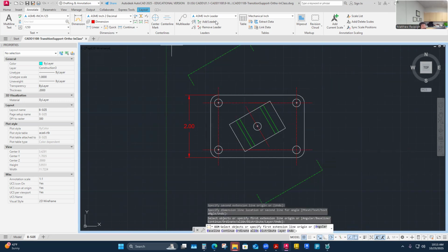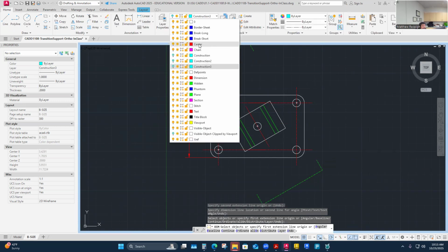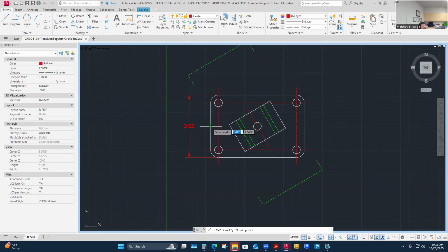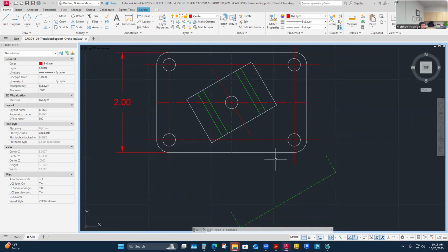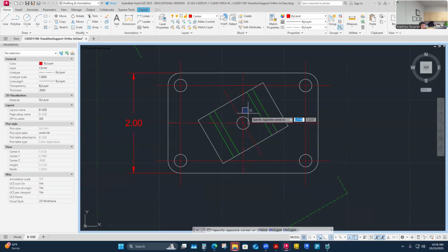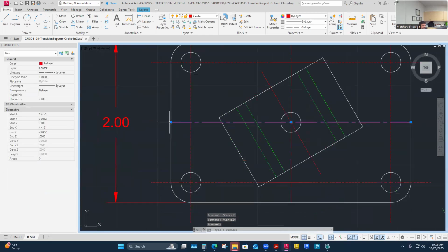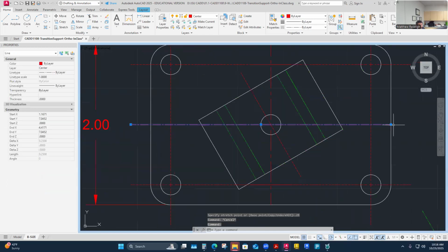But why I'm going off on a rant here is that I think I'm going to establish a center line of this part up here. And then these are going to be controls, I think, for me. So I'm going to have a controlled base surface and probably a controlled center line. I'm going to base some of my measurements on my holes and off this center line that I just drew. Yep, I think I'm going to call these some good controls to use. And I can go ahead and extend these out because I think I'm going to leave them on. I could call the front surface the control. I could start dimensioning from the front surface.